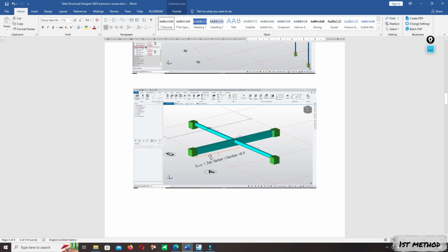This is the length of the beam. The total length of the beam is 6 meters, and the sub beam, yeah, intersects at the length of 3 meters. So we assume it as the restraint of the main beam. This restraint prevents the lateral torsional buckling, and the LTB length is equal to 3 meters, yeah.